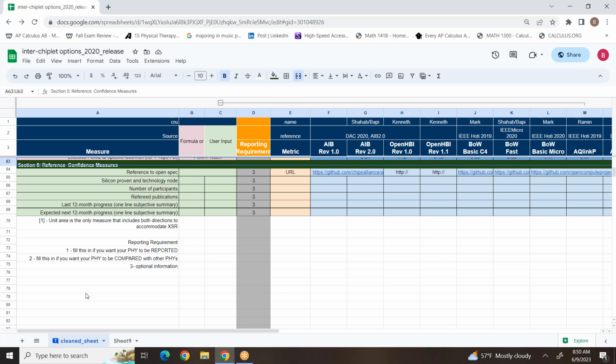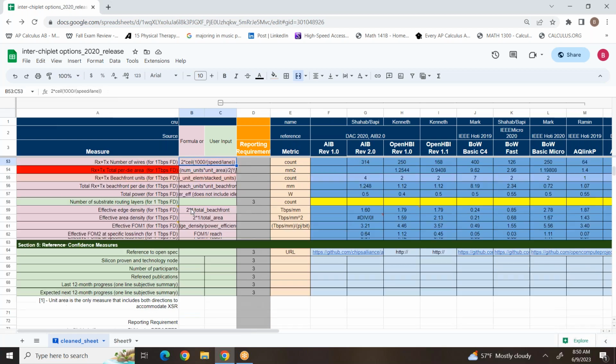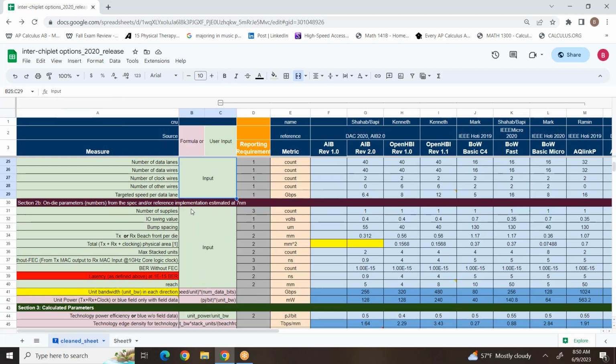Yeah, and I know that fight both on latency and energy efficiency, right? On some of these interfaces, you look at a massively parallel interface, it doesn't really matter. I mean, it matters what the energy efficiency is on the wire between the chiplets, but then what's the energy of the link layer, and implementation? Same thing with latency. Bump to bump doesn't really matter as much as end to end, information to information exchange. But yeah, first thing is defining it, because otherwise the merits. Exactly.